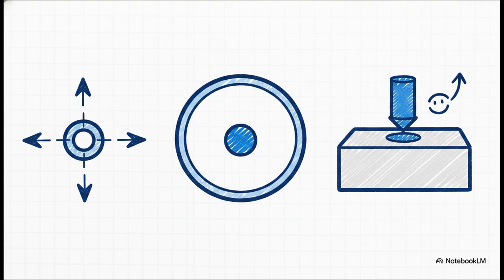So the crucial point here is what happens when we pair composite position with the maximum material condition, or MMC modifier. Magic happens for manufacturability. MMC sets the worst-case mating boundary. For a hole, that's its minimum size at its worst positional location. But here's the best part.